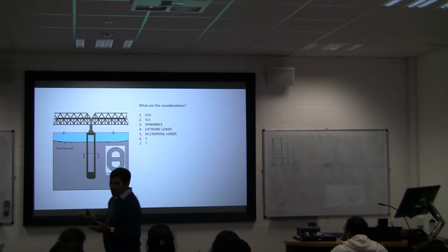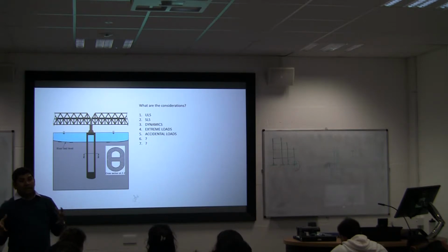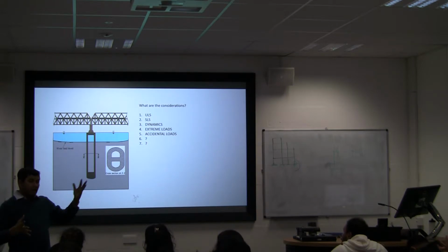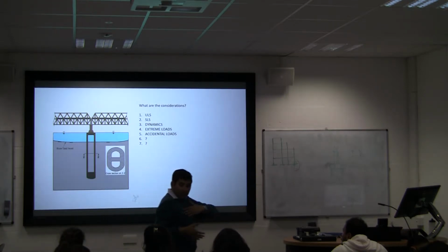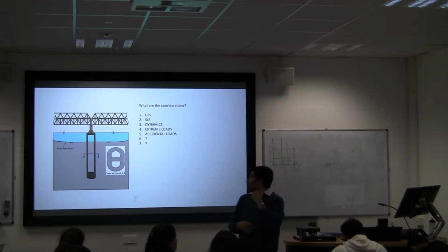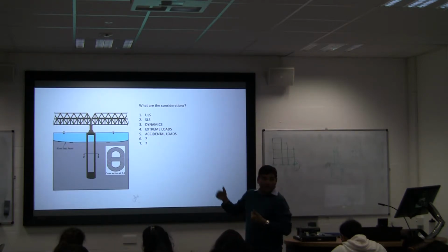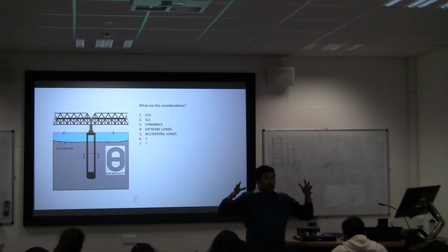Railway load. So I think you can also look into the maximum load that the bridge will carry, the sort of heaviest vehicle it will go through. Often military tankers are a design consideration. So you're taking into account the tanker, the large load that will go through, right? Accidental loads, yeah. They may impact. So you have to find out the ultimate maximum vertical load.